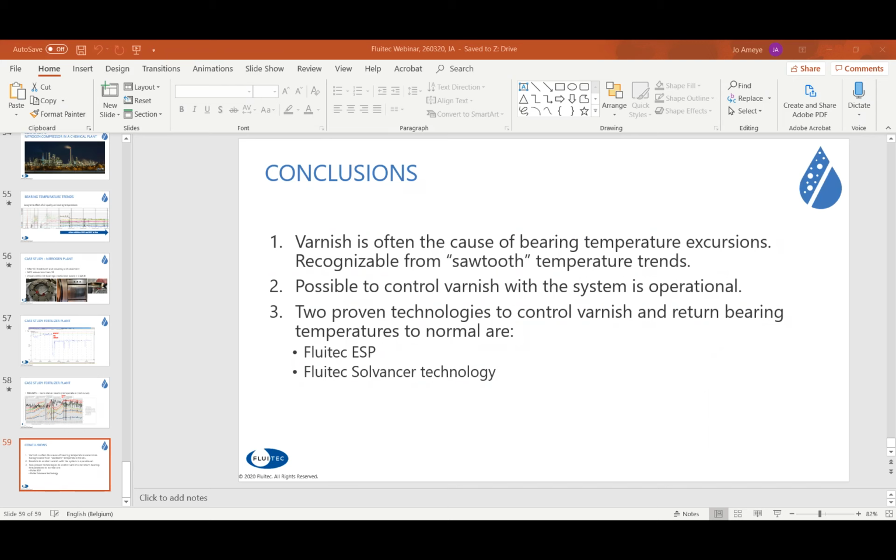So what's happening? Why in the past could we not see varnishing, or at least almost zero varnishing 20, 30 years ago, and now with the new oil, it seems it is more and more common? Yes, that's a good question, and in fact, it could be a webinar on its own. To be very short on that, I briefly touched on the solubility changes in group 1 to group 2 and group 3 oils, even beyond group 3 oils.